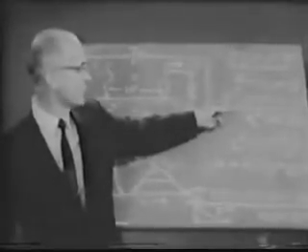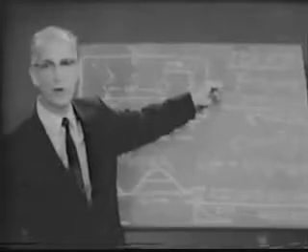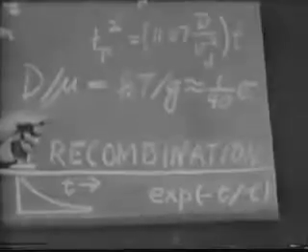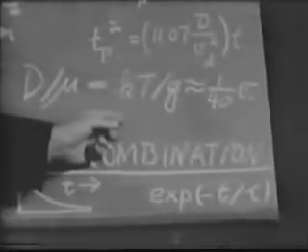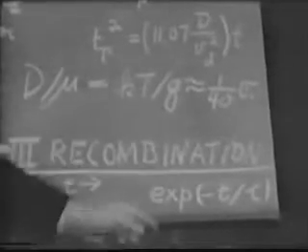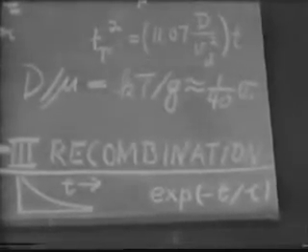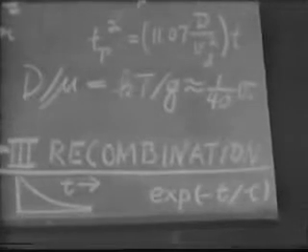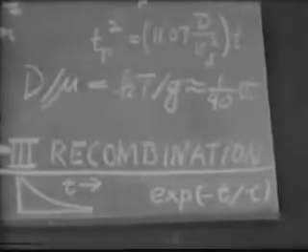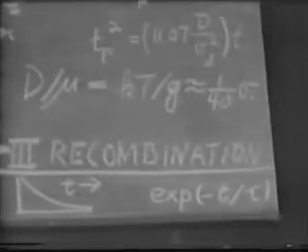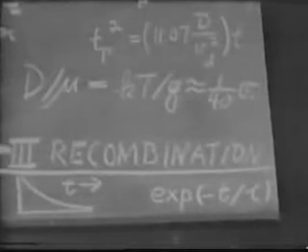The diffusion constant and the mobility of the holes have values governed by random thermal motion. The importance of thermal motion is expressed by the Einstein relation, which requires that the ratio D over mu be equal to kT over Q, in which kT is random thermal energy and Q the electron charge. This ratio has the dimensions of volts and is called thermal voltage.